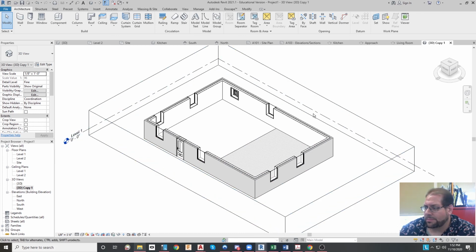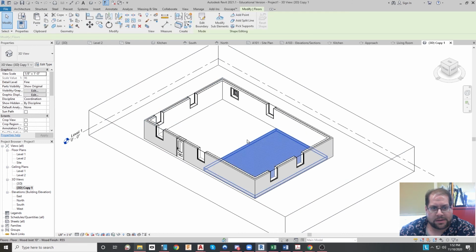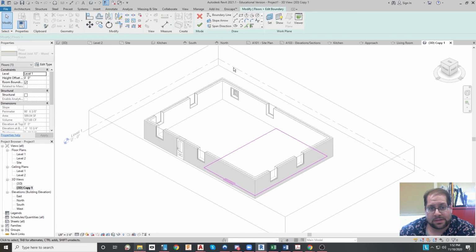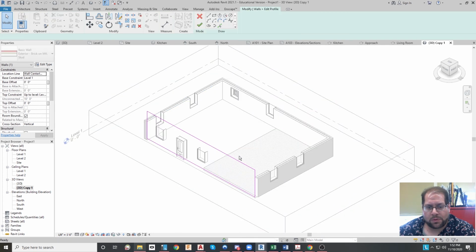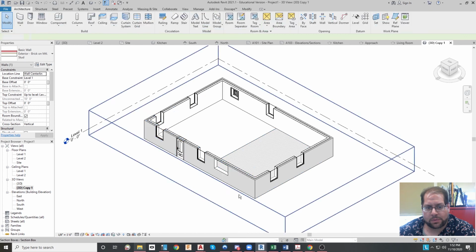And I think that's about it. Oh, and sketch mode and the modify button. I showed you the modify button before. And of course, sketch mode if you're editing something that was created with a sketch or creating something from a sketch from the beginning. Like stairs is another one, a roof. If I'm editing a wall profile, like if I wanted to change the way this wall looked and put a hole in it, I can do that by just doing that. And you can see that I just knocked a hole in the wall.